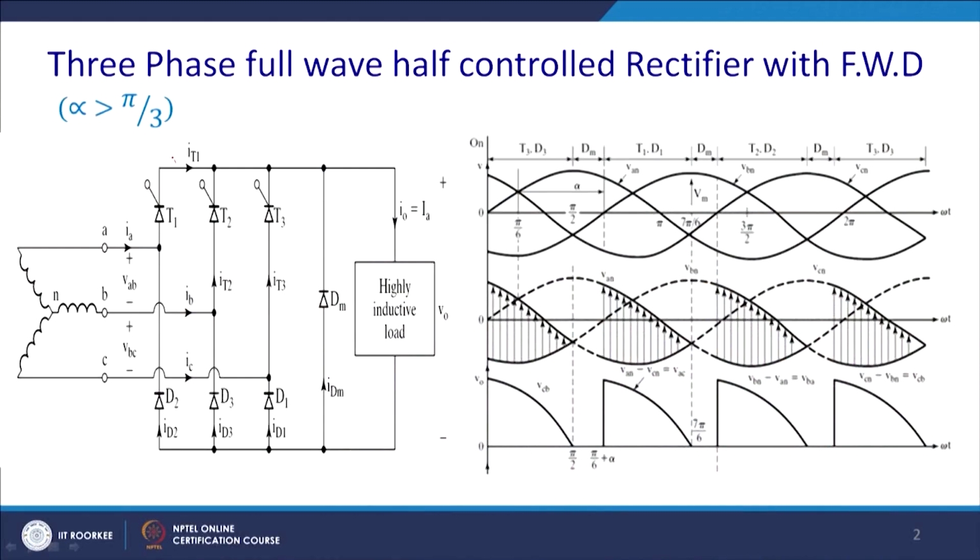We have chosen this because, till now, in many industrial drives, predominantly we had a DC motor, for traction for railways, let us say, and these are quite heavy machines in rating. For this reason, still now they are using this kind of controlled rectifier, and we just revisit the half controlled rectifier with the free wheel. You know these waveforms quite well from your power electronics courses.